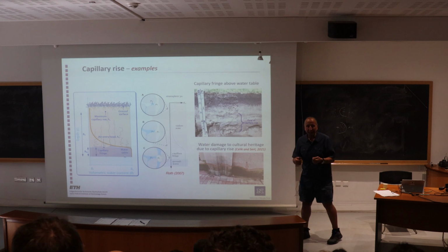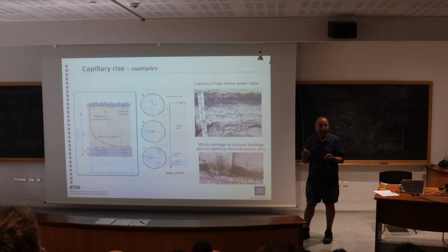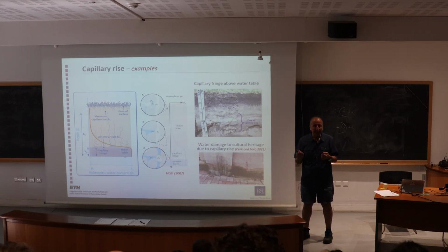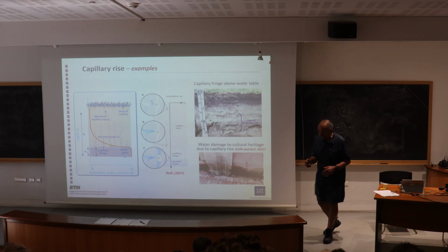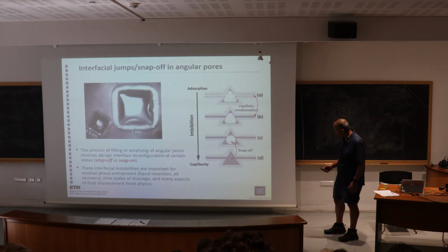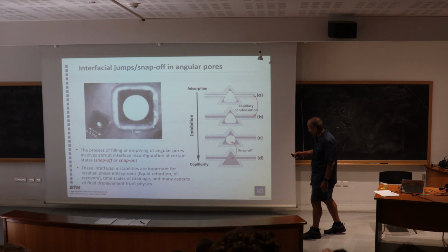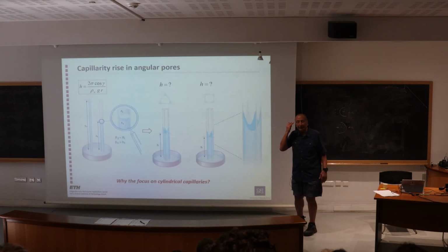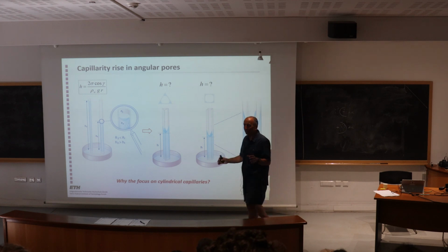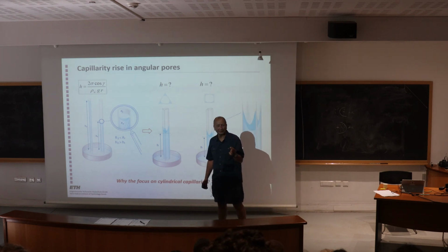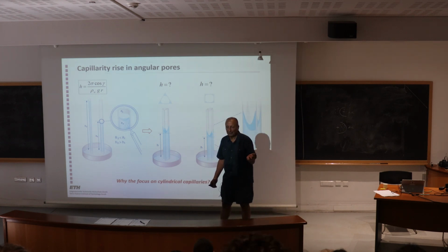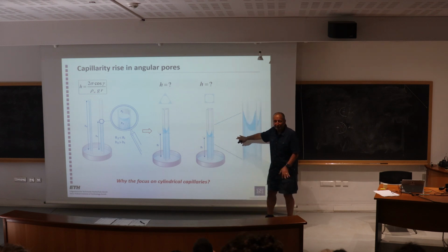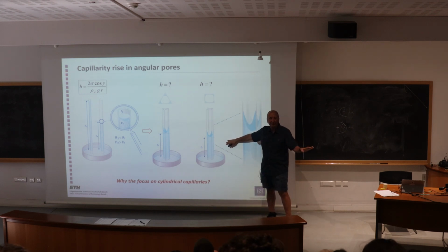So you can have an order of magnitude to guide your thinking just based on a concept that is quite simple, and that's the capillary rise equation. Okay, so I don't know why I'm doing this again, but so far in all textbooks, they talk about capillary rise in a cylindrical capillary, and why is that? So what I like to do is dispel and remove the fear from angular pores.